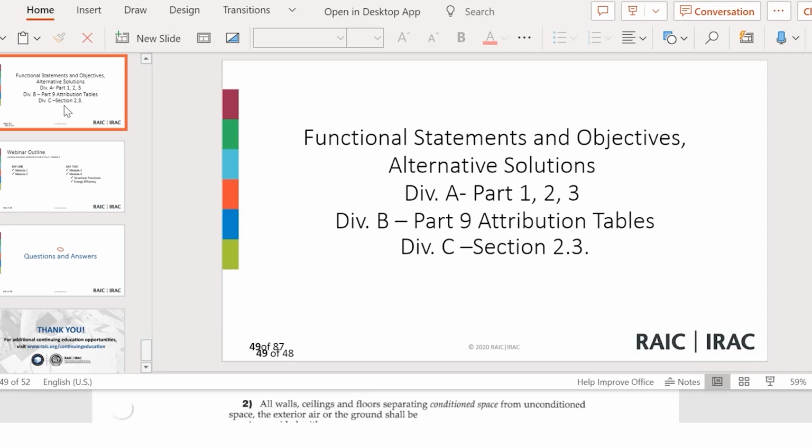Whether he wants sprinklers or not: sprinklers provide additional protection, and there are exemptions for buildings that have sprinklers in them. So see what the client's feeling is related to sprinklers, or make the recommendation of using sprinklers. We're fire protection engineers, so we always recommend the installation of sprinklers, but the code does not always require them. When it doesn't require them and you install them, it gives you leeway and less restrictive requirements. So there are trade-offs there.